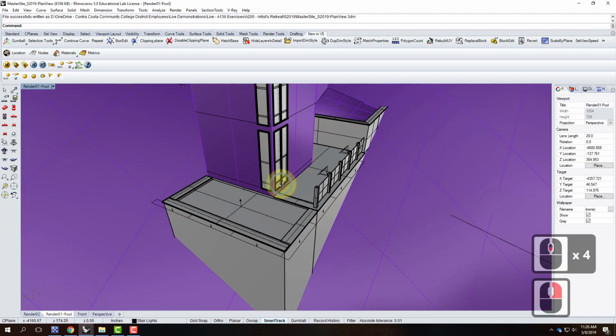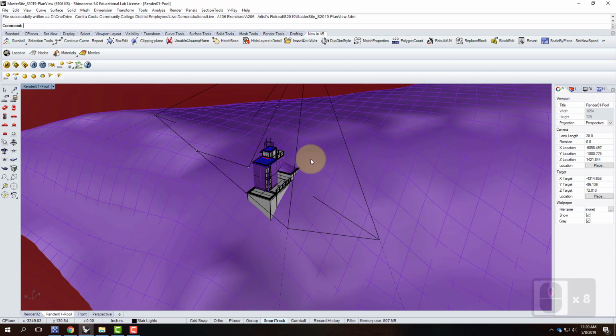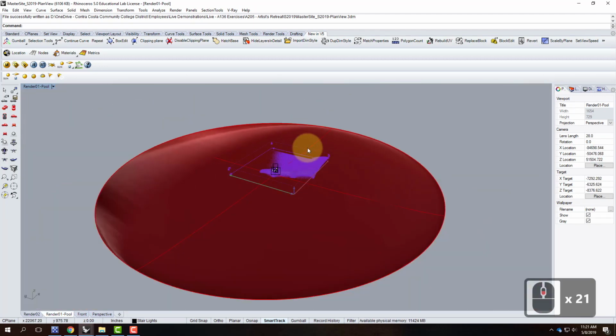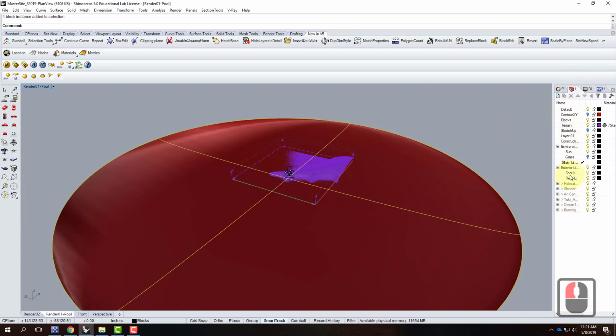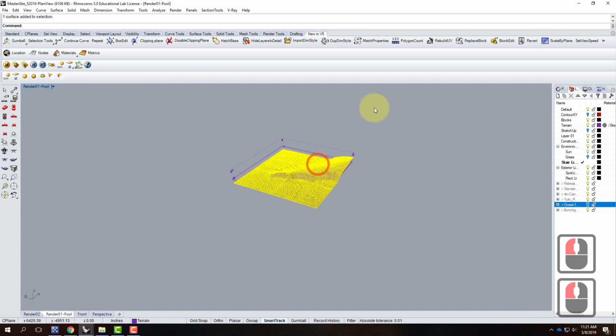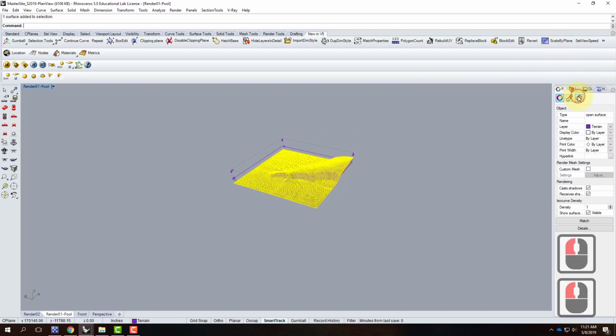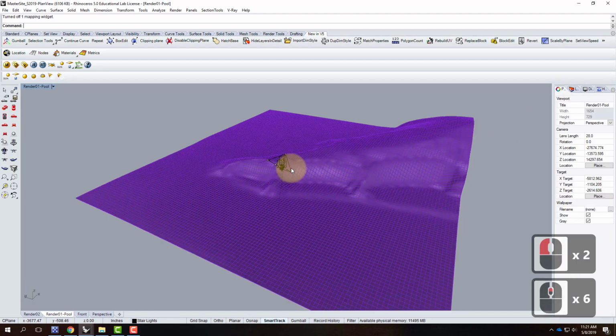Some of this is a repeat of what we did back when we did the section cut, the sectional perspective. I'm going to work in the same manner here to create that plan view. I'm not overly concerned about the ocean in this case, because it's not going to affect the plan view at all. I'm going to be much narrower than just this, so I'm going to turn off the ocean. I have a layer for the ocean somewhere. There it is. I should be able to turn it right off, and then I don't have to worry about that anymore either. I also appear to have my texture mapping on for the terrain, so let me hide the mapping because we don't need that mapping widget showing either.